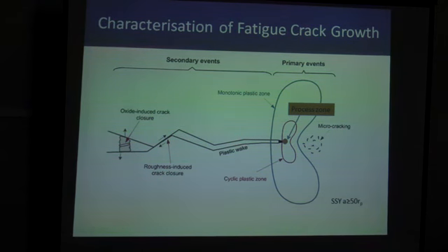But the current method is that we measure the crack closure, whatever mechanism it might be, and we measure the opening load. By no means is this a unique value, as I'm going to show you in a minute. We then go back to correlate the K, which quite often may not be valid.